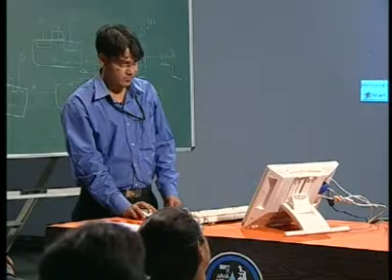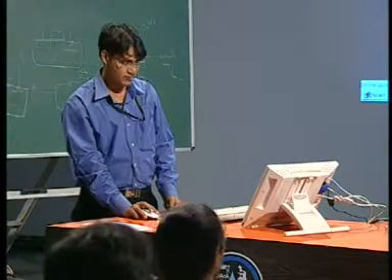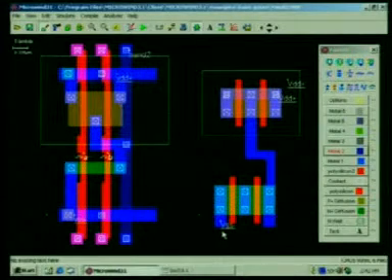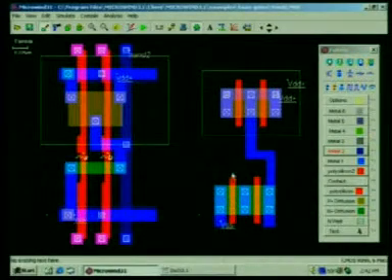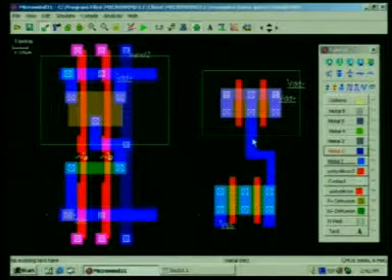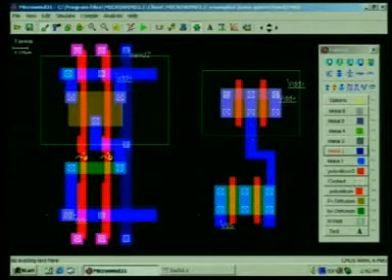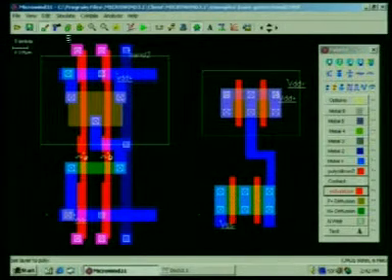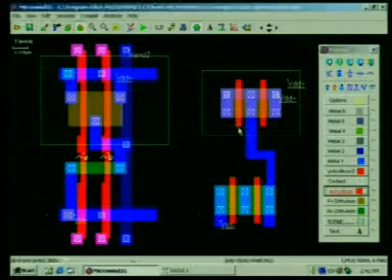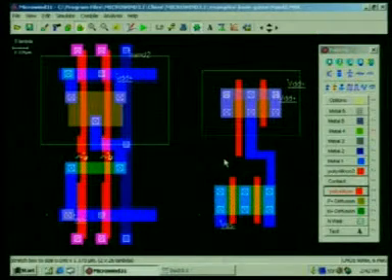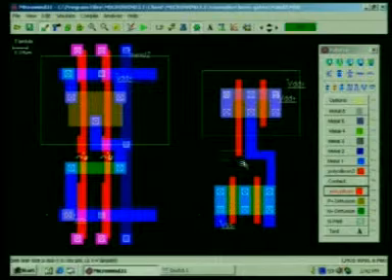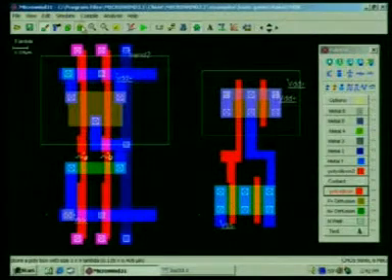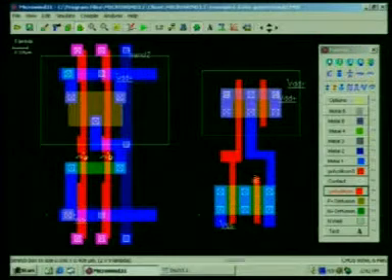Now, I will apply VDD here for polarization, VDD here, and VSS I have already applied. I need to connect this one now, because I have to make common these gates. So, I will just select this one, either you can select from here or you can just stretch that one like this.